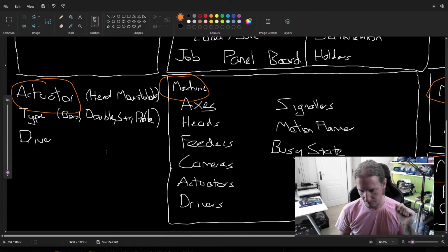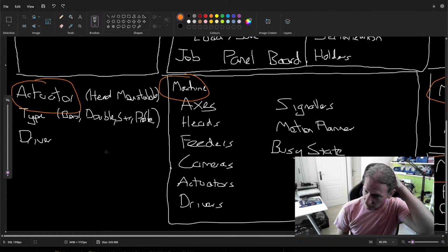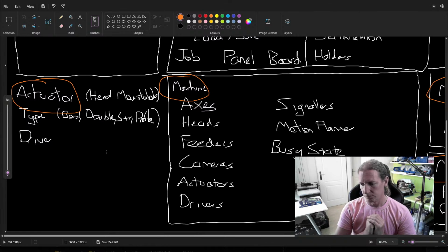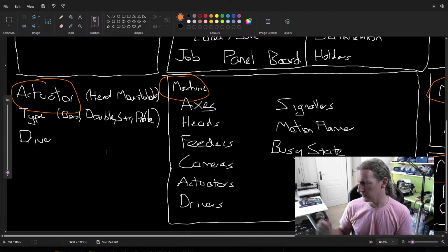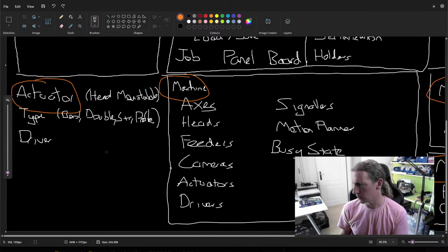So, for instance, what can happen is that you're building something, you've told the job to go, it's using a feeder to put a component on a circuit board, but somehow your stock count was wrong and you run out of parts, or maybe it mispicked a bunch of them and it's run out of parts, and now you need to get a new reel out or load more parts into the machine, and then you've got to reconfigure the machine for the new reel because they might be on a different side of the machine, or there might be slightly newer components, or an entirely different component, but you still need to finish that job before that job is done.